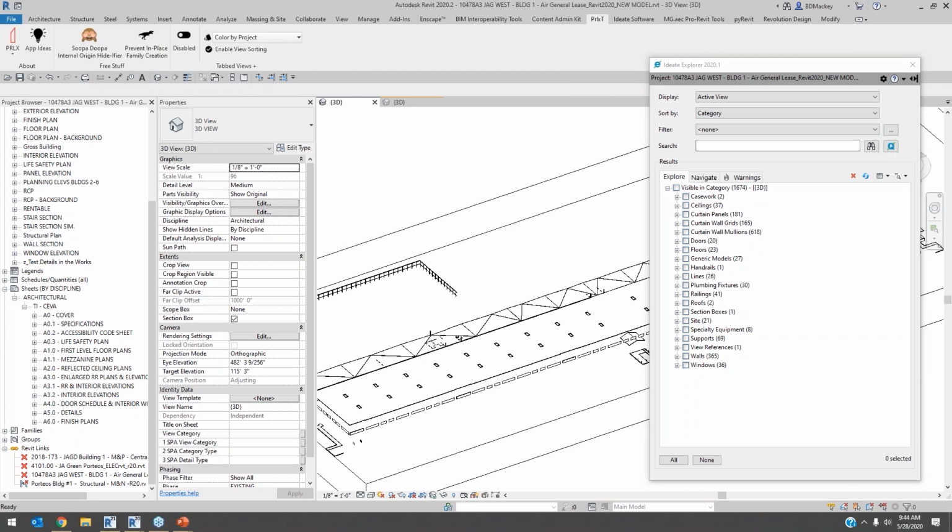So when we start getting in there and looking at this, I can switch the sort by to workset, and then I can start to see if they've got an FF&E, a finishes workset. Why on the finishes workset do I have things like gates, or I don't know what's not finish related? Why do I have mechanical equipment on the finishes workset? Things like that. So it's really easy to start coming through, and I'm just going to sort it by level because it would be very similar. Once I sort this out, it'll show me all the categories that are on this level. If this was workset, it'd say workset 1, whatever. Then I can start coming through here and seeing, oh, look, why do I have site stuff on the FF&E workset?